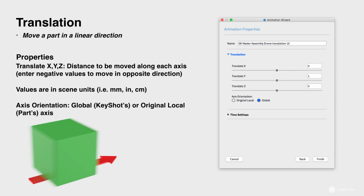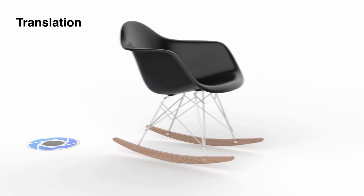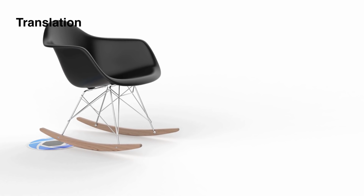And finally, we still have the option to choose the axis orientation, whether it's original local, which is going to be the local axis of that part, or it's going to be global, which is going to be KeyShot's world axes. So an example of a translation is going to look like this. It moves in one straight line, and then it moves back because I mirrored that as well.